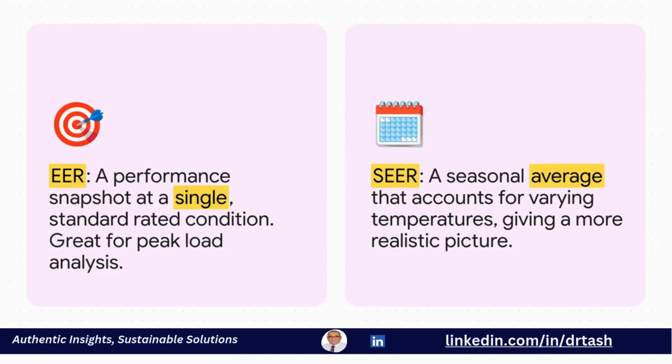Okay, now for a classic one, EER versus SEER. This really comes down to the lab versus the real world, doesn't it? EER is that perfect snapshot at one specific design point. It's great for figuring out your peak load performance. But SEER, well, that's what gives you the practical, season-long picture. It factors in part load performance, which, let's be honest, is a much better predictor of what your annual energy costs are actually going to be.